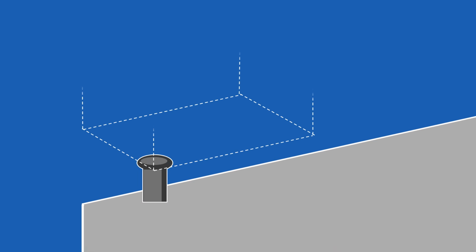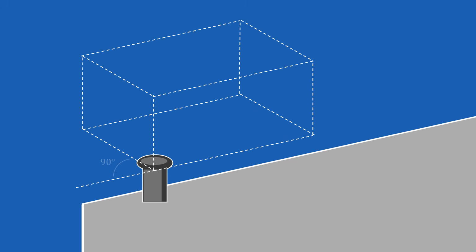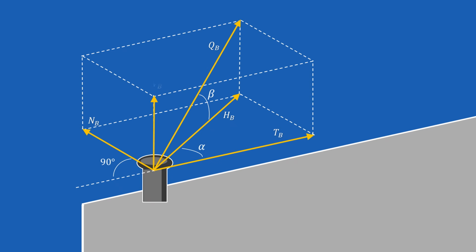Geometry now becomes critical. Mooring lines are inclined both horizontally and vertically, and this inclination has a direct effect on the tension in the line. Because of this inclination, the actual tension in a mooring line is greater than the horizontal force it is resisting. If a line forms a horizontal angle alpha and a vertical angle beta, the line tension can be calculated using a trigonometric relationship. From this tension, the longitudinal and vertical components of the force transmitted to the dock structure can